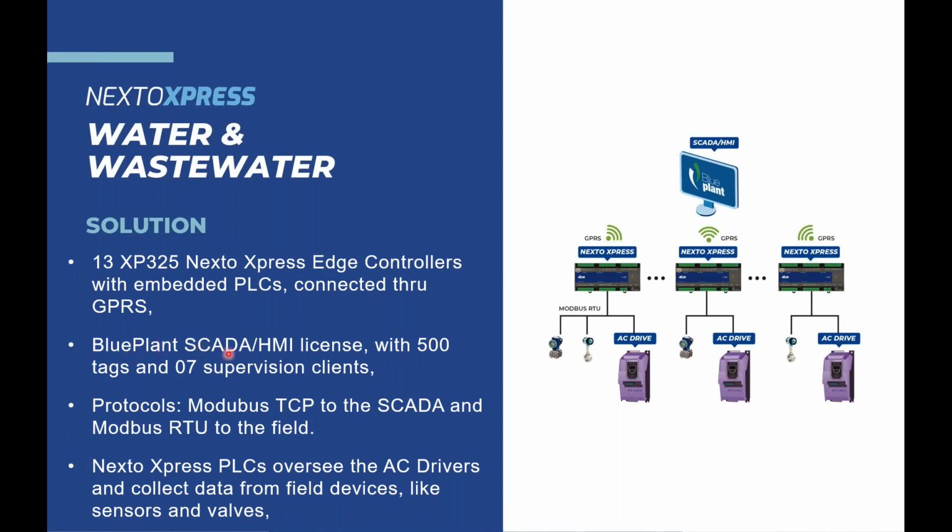Blue Plant was a SCADA system going to the control center, and as a requirement from them we were using Modbus TCP going from each unit to the control center and Modbus RTU to the field. Some of the old devices they have in the field were not connected. They didn't have Ethernet.